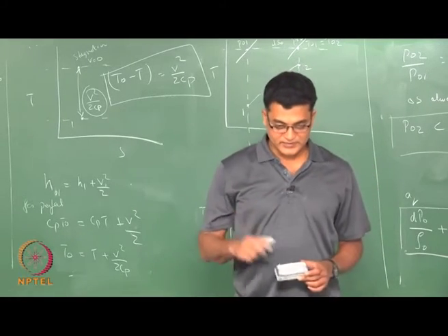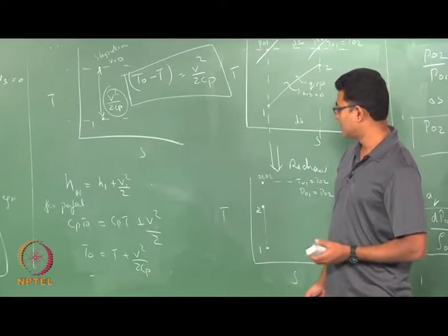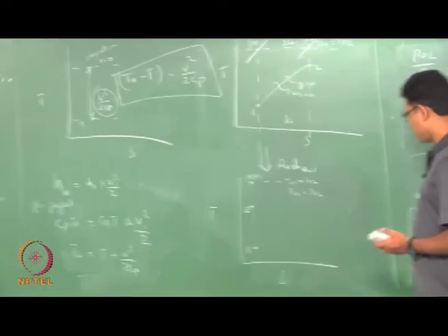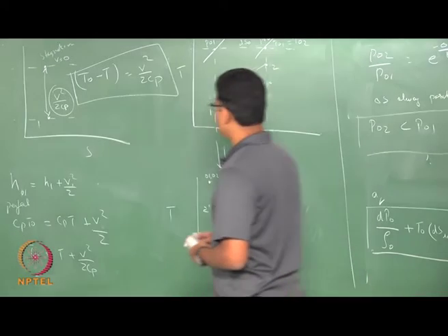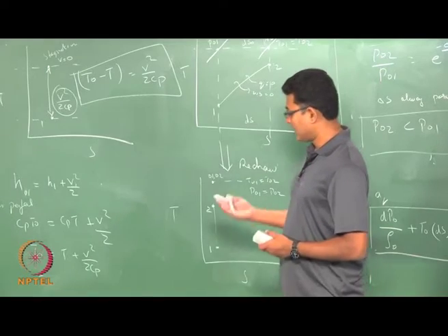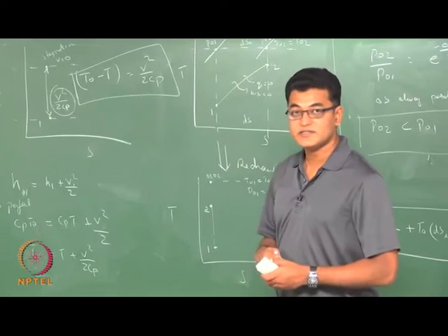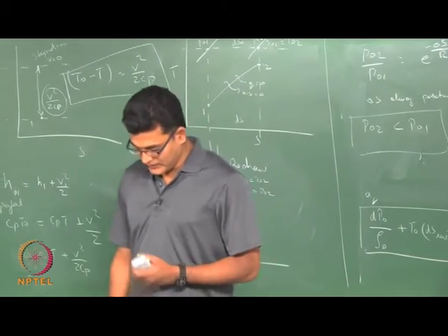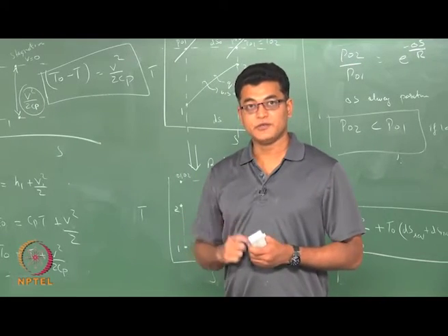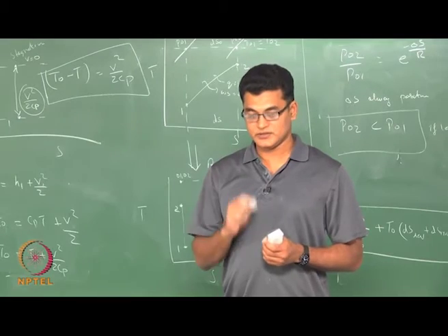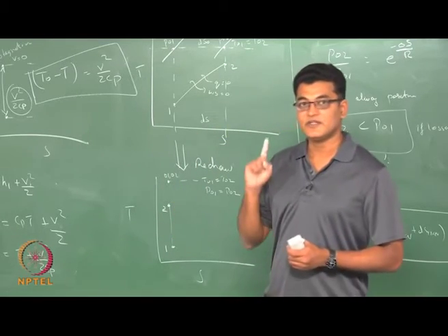What we have learned today is the concept of stagnation condition, the possibility of a new quantity, a stagnation temperature, and associated with it you have stagnation pressure and hence other quantities as applied to your energy equation as well as your ideal gas equations. Those relations are derived from your thermodynamics laws, energy equations and your Gibbs relations. So, for a case where there is no heat and no shaft work, if the process does not involve losses, you have T01 equals T02: the stagnation temperature associated with state 1 is the same as the stagnation temperature associated with state 2 if they undergo a process without heat, without shaft work and no losses.